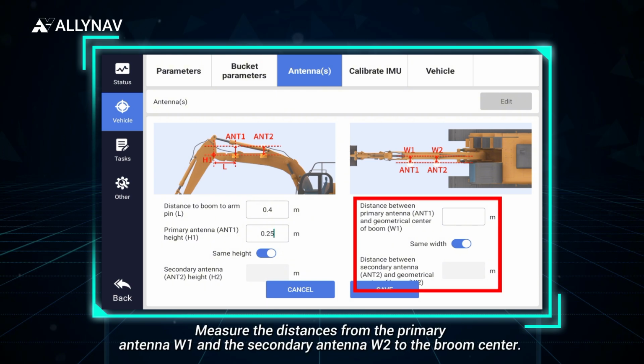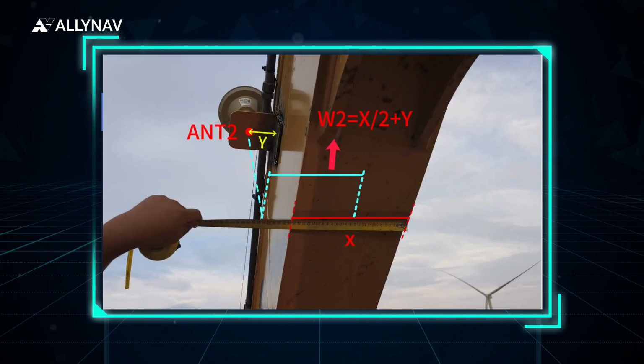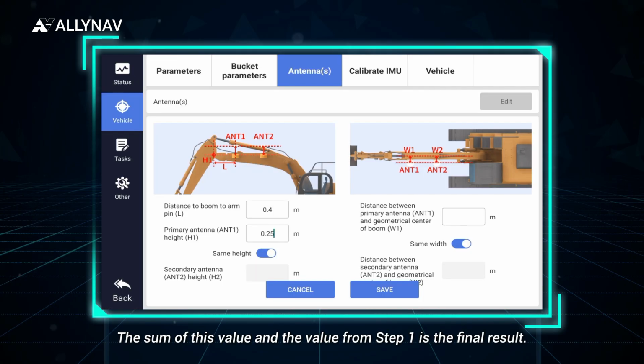Measure the distances from the primary antenna W1 and the secondary antenna W2 to the boom center. Step 1. Measure the boom width and divide the value by 2. Step 2. Measure the distance from the antenna to the boom edge. The sum of this value and the value from step 1 is the final result.